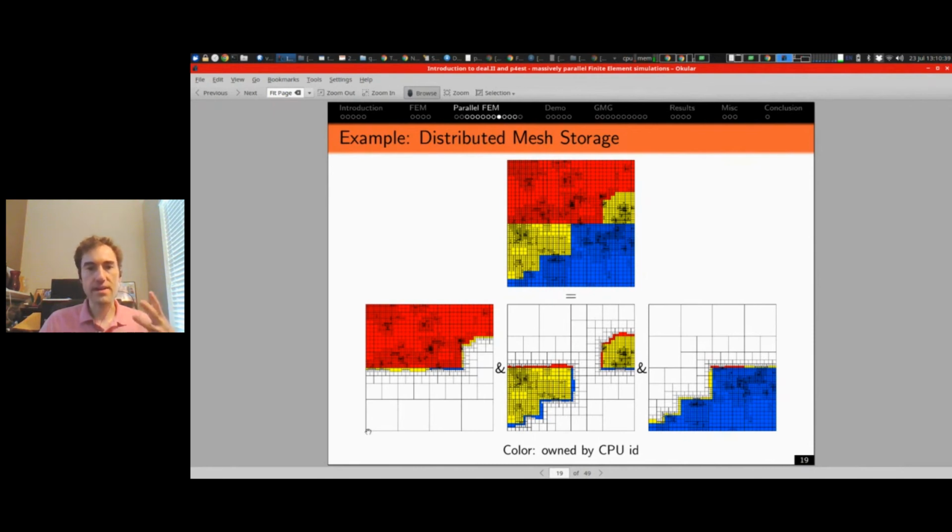So we're constructing basically these two things next to each other, right? So p4est knows what our cells are, and deal.II also knows what our cells are. And basically, p4est is then not used during most of the simulation, right? So we go into p4est when we want to do a rebalancing, a save or a load, or if we want to do a refinement. But the rest of the simulation is completely decoupled from p4est.